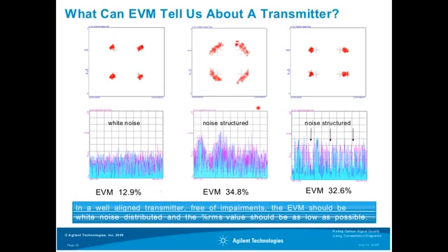In addition, if we look at the error vector magnitude diagram here, with a phase distorted constellation diagram caused by the DFB source, we can see a noise that is structured and that is not even white. And again, we would probably expect that this slight imbalance in the gain would not reflect any structures or impairments in the error vectors.